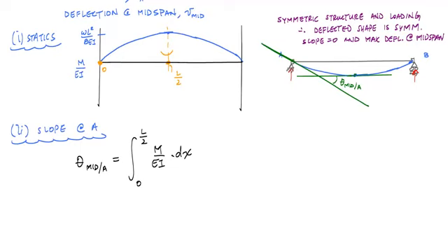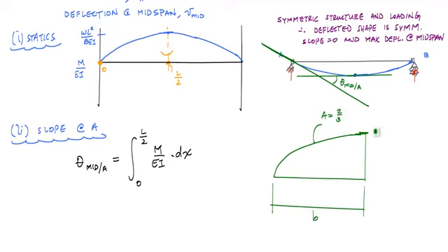And for a parabola, or half a parabola, where the slope at one point or one end is 0, what I found is that this area is equal to 2/3, and let me call this the base, and this distance the height, 2/3 BH is the area. The centroid, which I will put right here, C, is 3/8 B from the fat side, if you will. And this distance from the skinny side is 5/8 B.